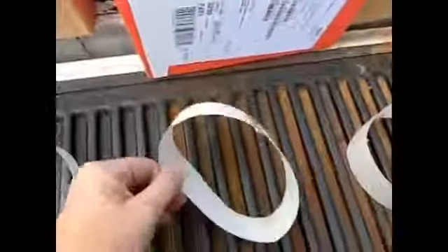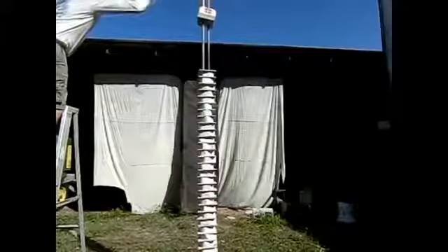The columns in the towers were thicker and stronger below. But in order to give benefit to the pile driver theory, I wanted to make the weakest walls possible, even if it didn't meet deflection codes. So I used paper and matchsticks for my walls. Raising the upper floors and dropping them on the lower floors, I didn't get the results I was looking for. Instead of accelerating down like Tower 1, the upper floors decelerated, even on the weakest of supports.